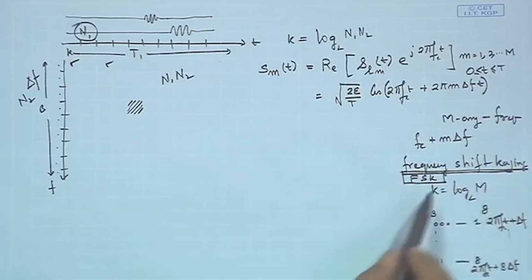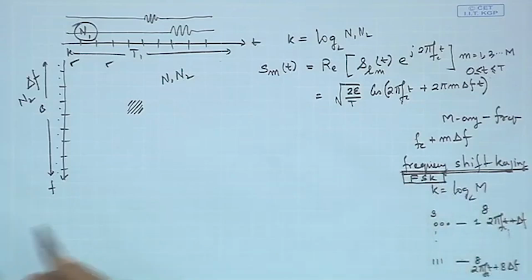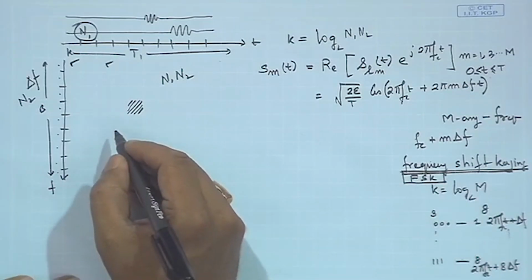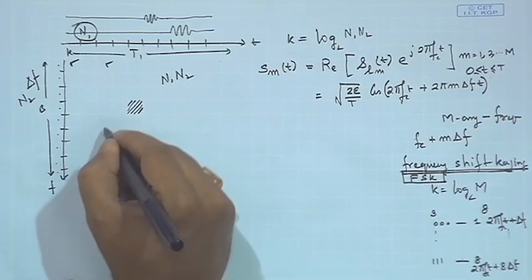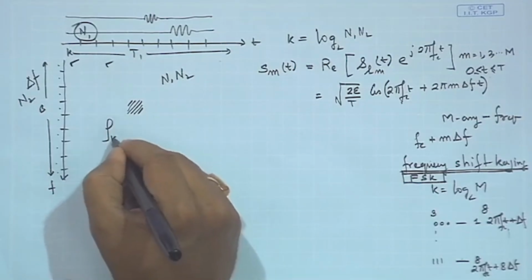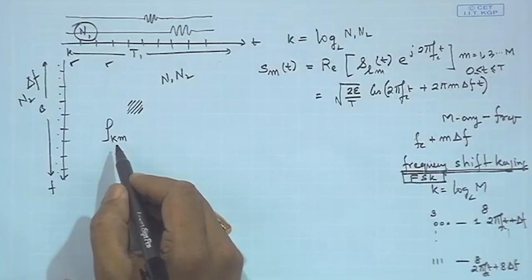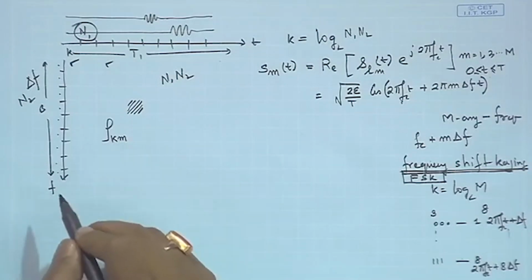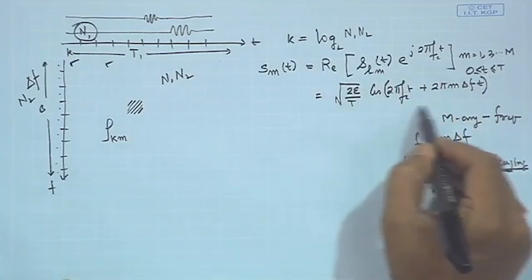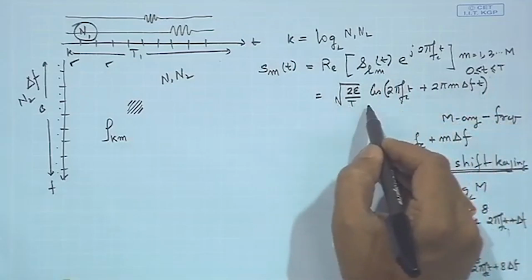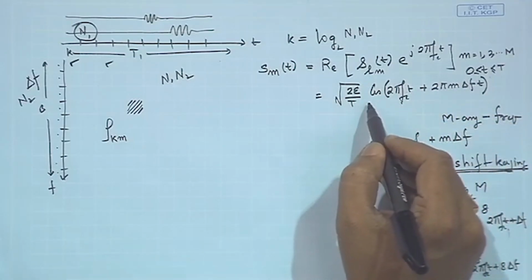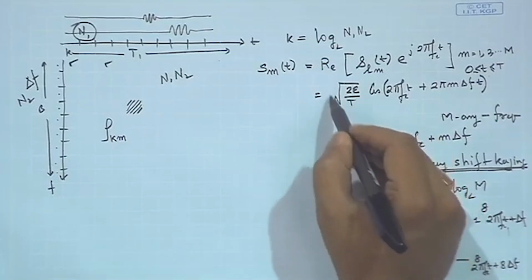So, once we have this, one of the interesting properties that we should look at is the signal correlation, and we define it as rho k m. Now, why we study this would be very clear within a few minutes. So, rho k m we define it as the correlation, and you could also see from here, comparing this with the phase shift keying, the amplitude is fixed.